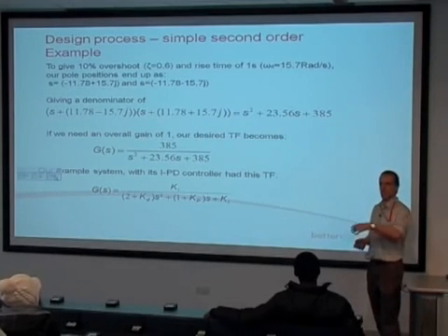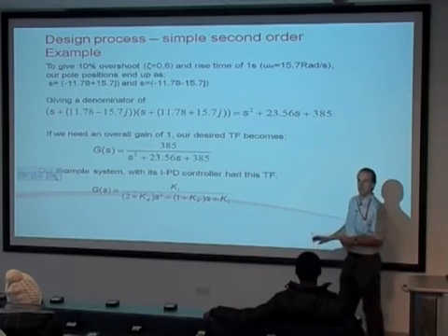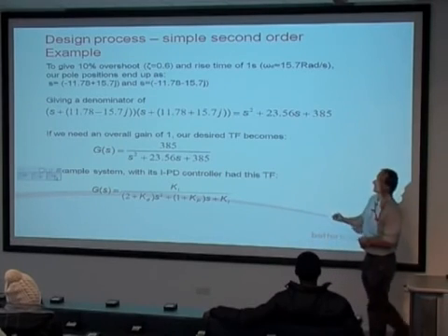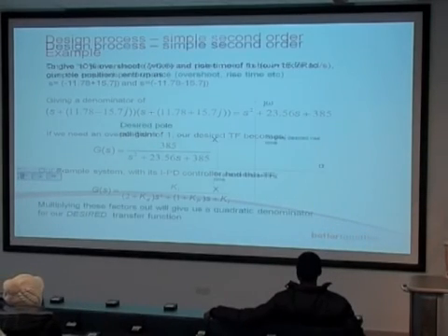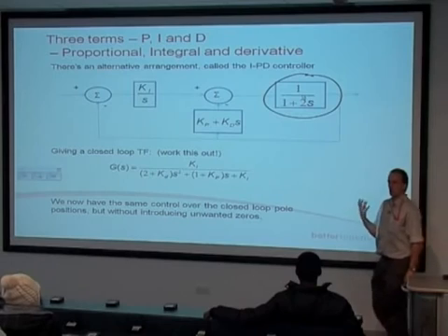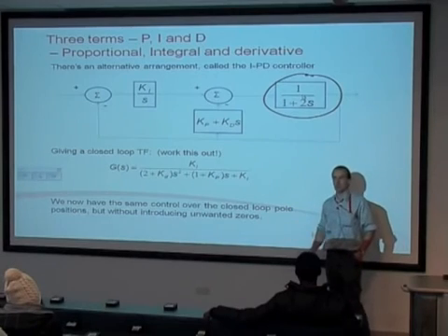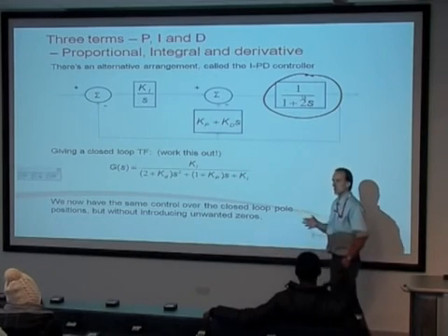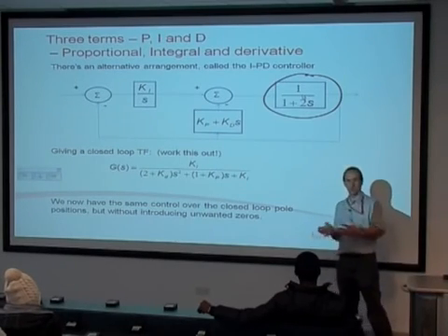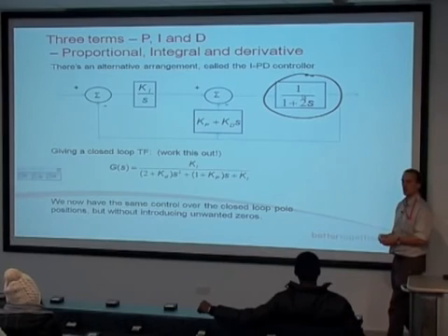Okay, so I know I slightly rubbished them earlier on by glossing over, but the key thing about these algebraic methods, these methods only work correctly if we've got an accurate model of the system in the first place. We need to know the model transfer function for these algebraic methods to work. If we do, everything's dandy, no problem at all. But if you're in a situation where you don't have that model, and maybe you haven't got the facility to do a quick frequency response test to evaluate the transfer function, that's when the empirical tuning methods come in.